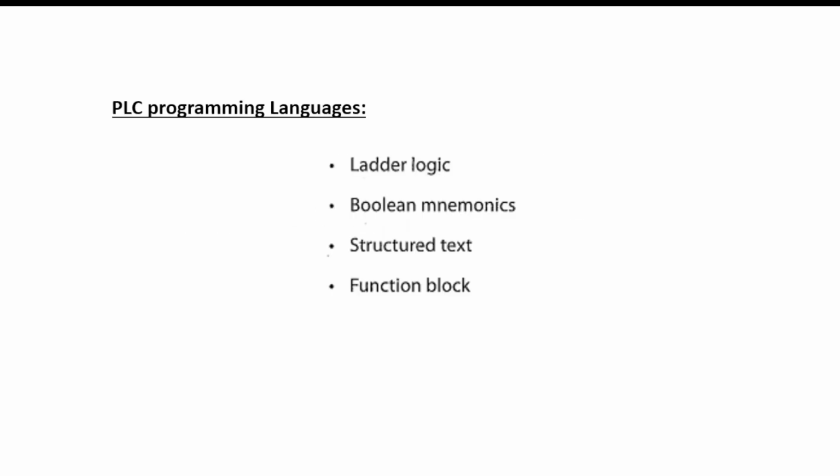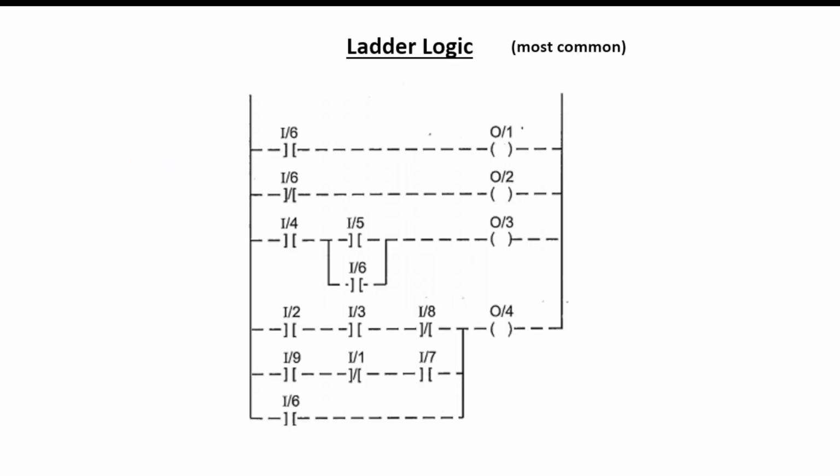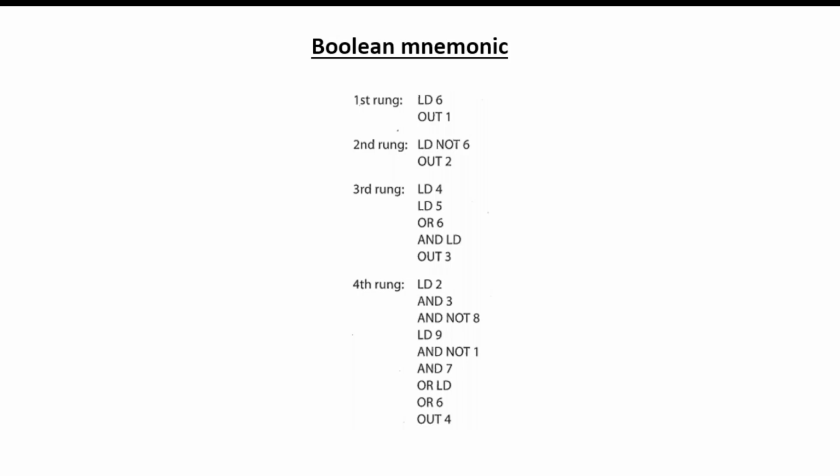There are a number of different PLC programming languages available to the average user: ladder logic, Boolean mnemonics, structured text, and function block. This is the method of inputting instructions into the PLC program. Ladder logic is by far the most common, and we will be focusing on this one for the duration of this presentation. But some of the others that are going to be used in different applications are Boolean mnemonics,